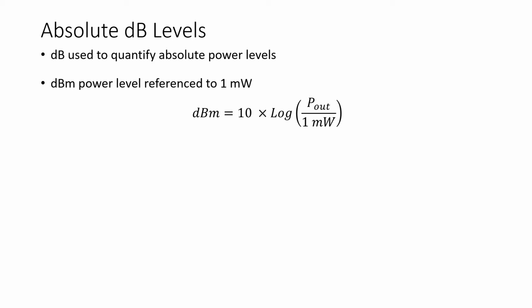So if you've ever had the telephone repairman come to your house and check the signal strength at the box outside your house and told you the signal level was 80 dB, this is what he was talking about, 80 dBm. If you've ever had satellite TV and you run a check on your satellite dish and it shows you numeric values on your television for the signal of different satellites, that value is expressed in dBm also.